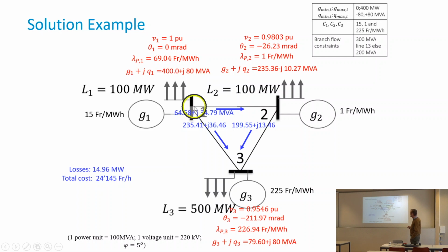Well, if we had only active power, as you may know from your basic AC course, the power on an AC grid has a real and imaginary part. The only useful work is done by the active power. The imaginary power has an average of 0. It is power that during half a period flows in one direction and during half a period flows in the other direction. So it's useless from the viewpoint of work. So we could say we don't care.